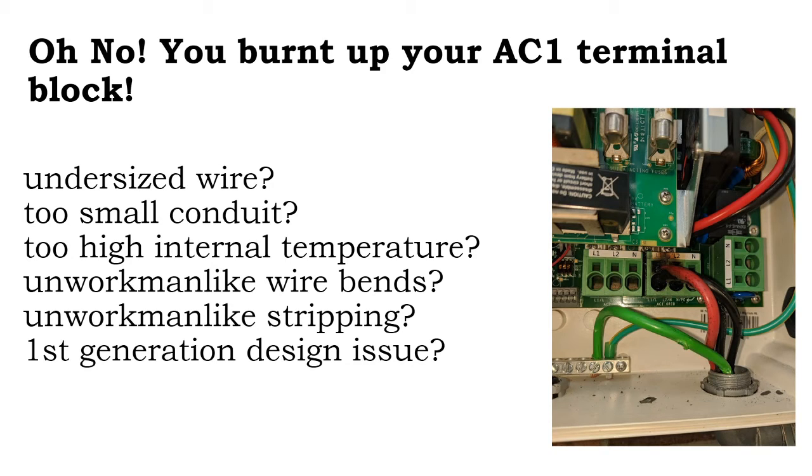Was the wire too small, and so more current flowed through it than what was supposed to, and that caused the wire to smolder and burn up? Was it the heat from the inside of the conductor? Was the temperature of the inverter too high? Maybe it was an indoor inverter and it was placed on the south side of the building and it heated up too much?